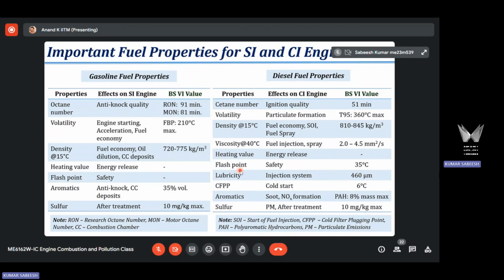So you know flash point temperature is the ability of the fuel to produce a momentary flash in the presence of an ignition source. How quickly the fuel forms a momentary flash is indicated by this temperature. Diesel won't form a momentary flash because the flash point temperature is high, meaning that it will form a very lean mixture that cannot be ignited even in the presence of an ignition source. So it is a safer fuel for storage and transportation.